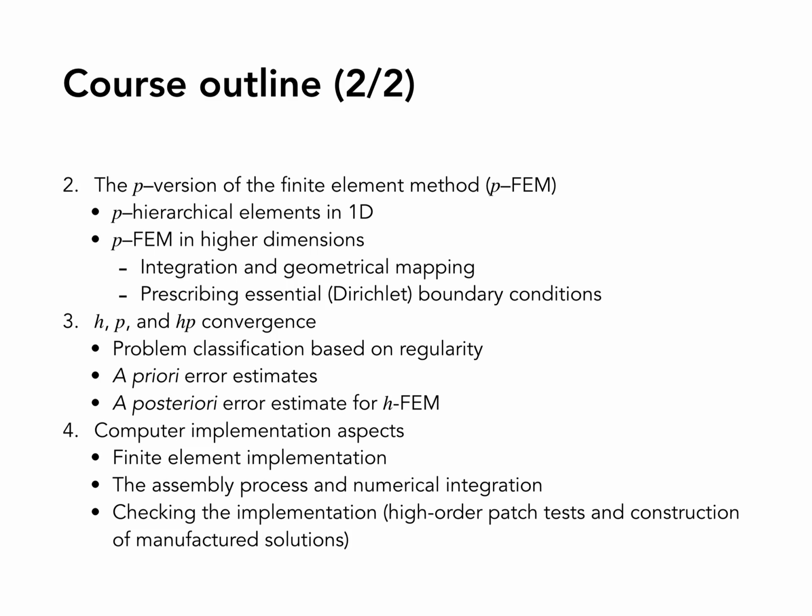The best you can do with h-FEM is to reduce your error algebraically, but with p-FEM you can reduce it exponentially, and that is very powerful. If your problem is smooth, and we will look into those ideas of what are smooth problems and what are singular problems, so we will be talking about singularities and so on, then the p version of the finite element method is much more powerful to reduce the error.